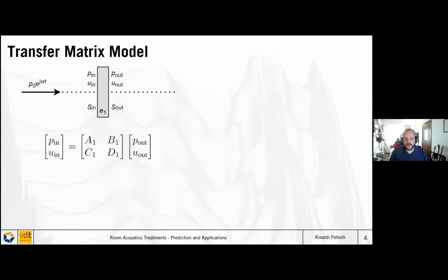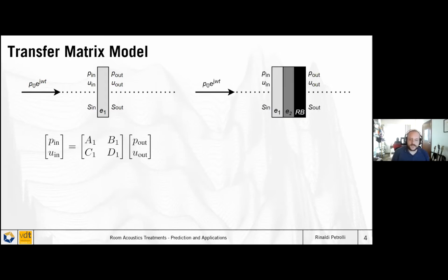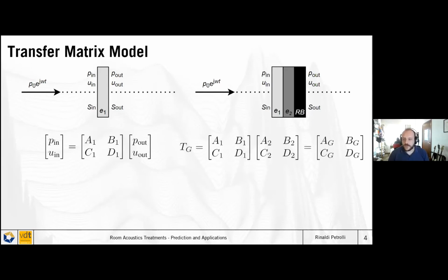But the principle here is that we can consider the continuity in pressure and velocity from one layer to the next. So we can use the surface impedance of one as the surface impedance of the next. So whenever we have a multi-layered system, like let's say a Helmholtz resonator, where you have a perforated layer, you have a porous layer, and then you have a rigid backing, you can start to stack these matrices and different 4 pole parameters, so you can actually evaluate all sorts of configurations.